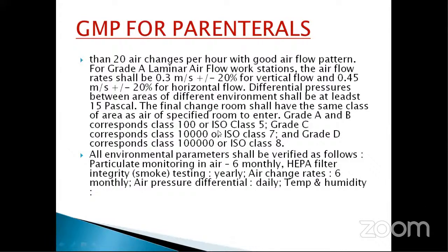So in the ISO class, that is also classified in this way. And all environmental parameters shall be verified as follows: particulate monitoring in air, at 6 monthly intervals we have to measure it. HEPA filter integrity, we have to see how far the HEPA filter which is provided is working. Its integrity testing is done every year.